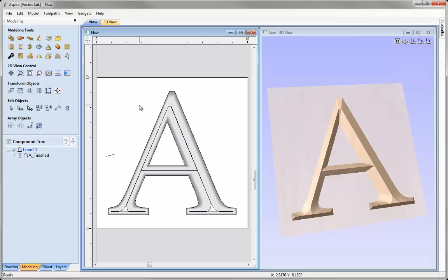Now you might think with something like this we could achieve the same effect by using an angled tool and just running it around the vector. But unfortunately we'd get neither the sharp corners on the inside or this constant height, because to maintain a constant height on a letter like this, the angle has to vary as it travels around the shape. If we let the angle remain constant, then the height of the letter would vary as it got wider and thinner. So that's why this is not achievable just by using something like the prismatic toolpath.